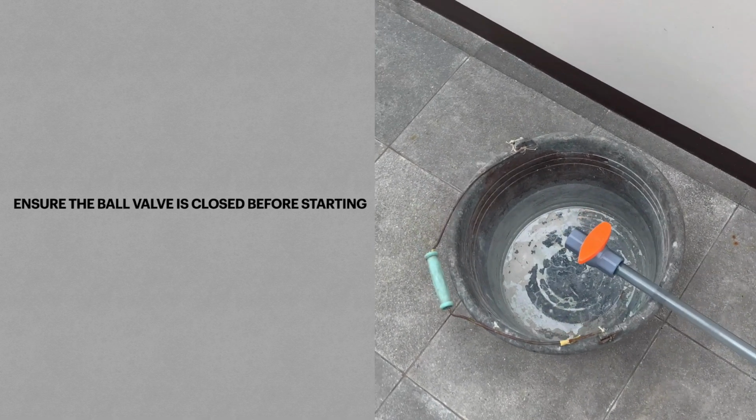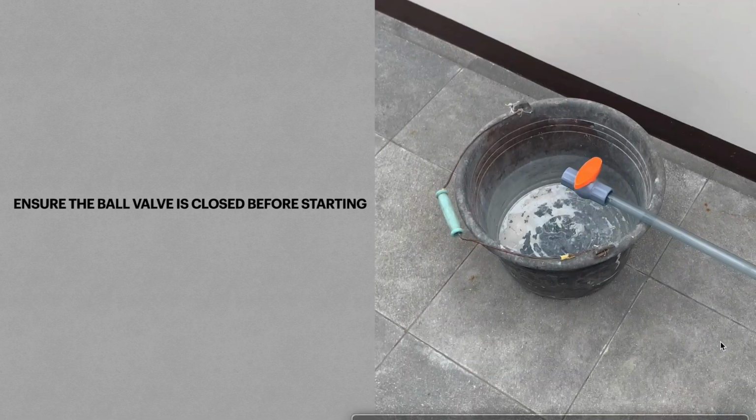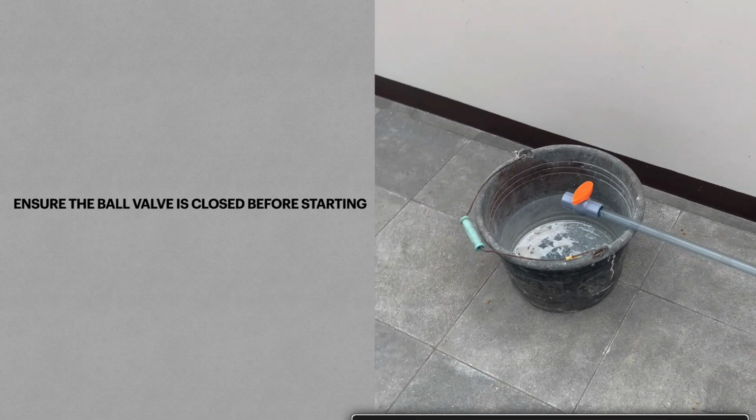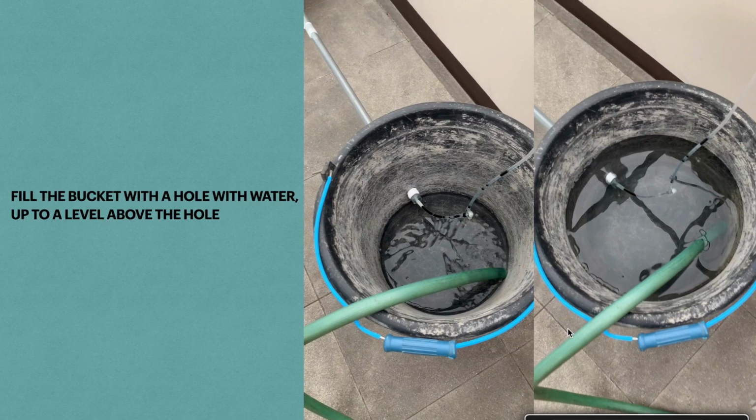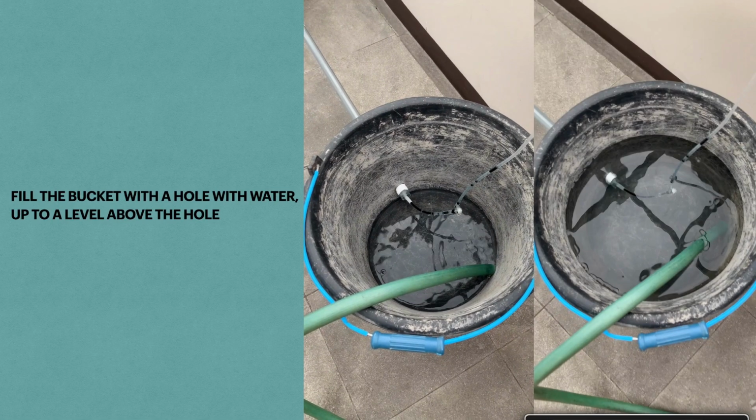The procedure for this experiment is not complicated, and it will be explained in the following slides. Before starting the experiment, it is important to ensure that the ball valve at the end of the pipe is closed. This is done so that the horizontal pipe is fully filled with water. Now before the bucket is filled with water, ensure that there are no bubbles inside the pipe. Should there be any bubbles inside, slightly open the valve at the end to let some water out. If there are no more bubbles inside, close the valve and throw away the water from the container bucket.